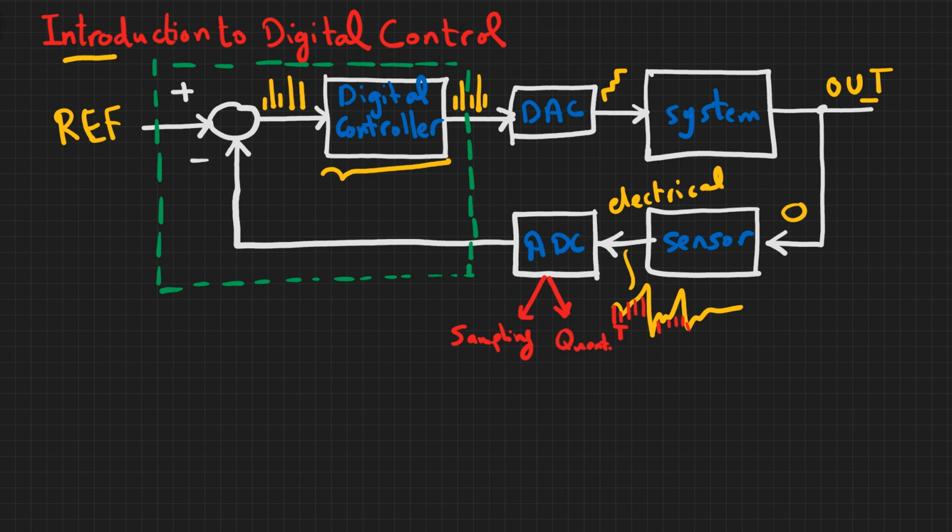Okay, we will explain those two maybe later in more depth, but the basic idea is that you should take enough samples to consider all the variations in the signal, and in the quantization you need to represent each sample by a discrete number at the end. So in order to do that, you need to divide your amplitude range into a certain number of levels, and then you approximate each sample with the closest level. So this is the quantization step.